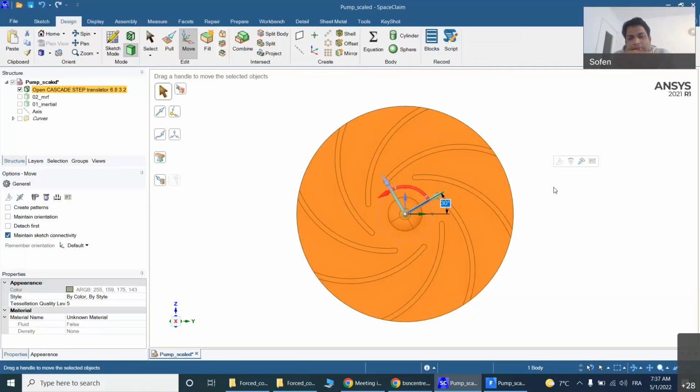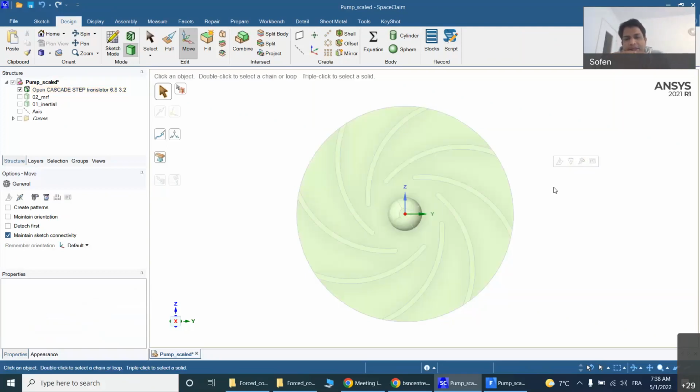This is one approximation where we solve it in a steady state, right? But again, suppose we have huge computational resources. I have a cluster computer, or I have access to ISC or some supercomputer where I can run it. So in that case, I can go for the transient simulation. Means instead of changing the blade in the geometry itself, I will allow the mesh to be rotated in the solver itself, right? That kind of simulation is called a sliding mesh simulation, where the mesh actually slides physically in the solver, right?